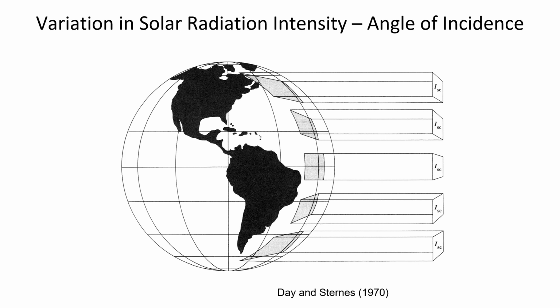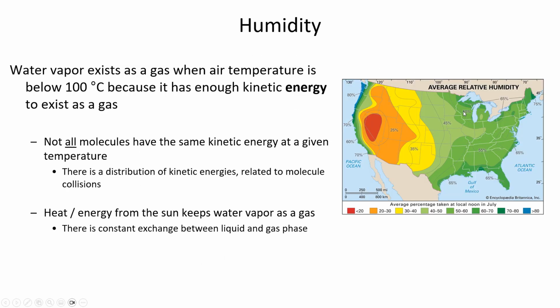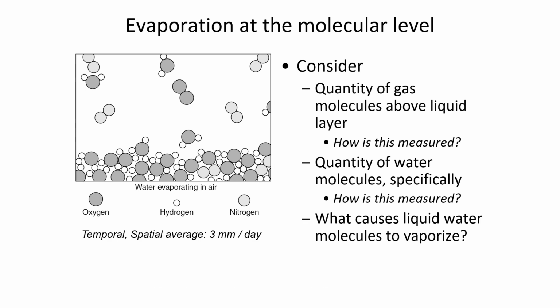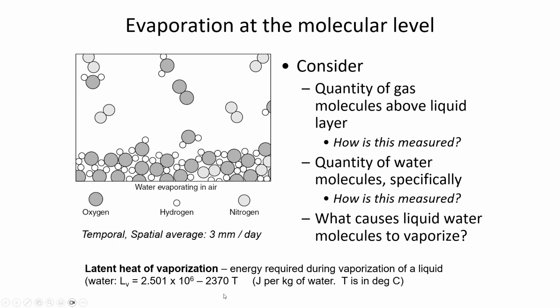So I'm asking you to look at a certain day in 2005 and predict how much evaporation could occur during that day based on the sunshine that was available. And when you know how much sunshine is available, then you can combine that with the latent heat of vaporization and estimate the evaporation amount. The sun is providing the energy. This constant tells you for a certain amount of energy how much evaporation there is.